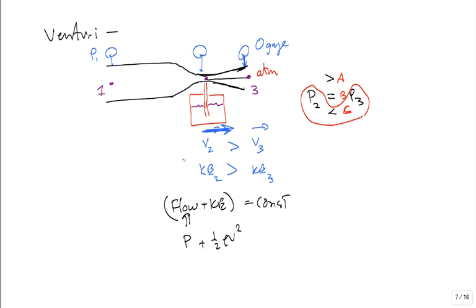It's sucked up. Is there a pump to push it up? You probably haven't even seen a carburetor in your life, right? Automobiles used to have carburetors. How did that work? Venturi effect. The necking down of the airflow draws the little gasoline up through the needle area.